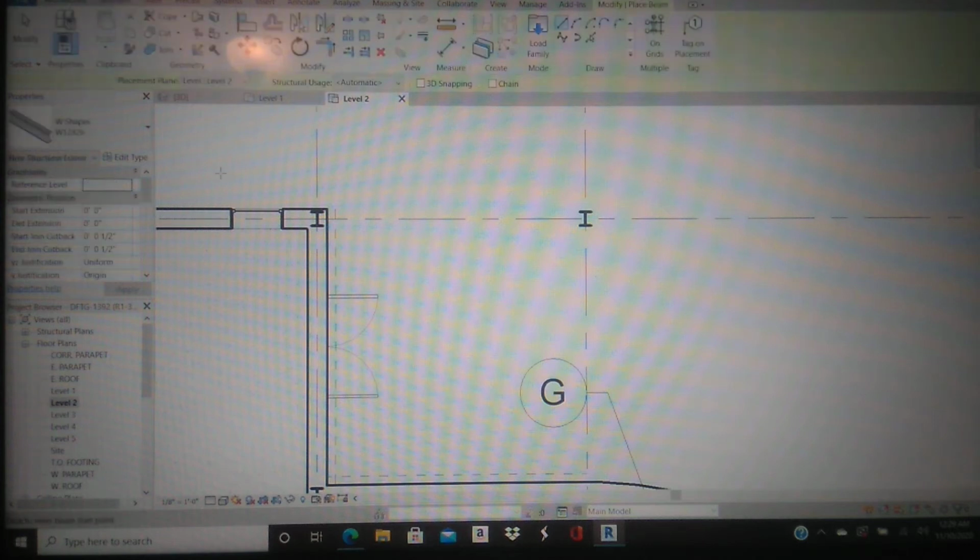So let's go ahead and click beam here, and we do have the 12 by 26 loaded. As stated, whatever you guys have loaded, I'm fine with that. We don't have to add tube steel, which is what I think the book is really calling for, a 6-inch by 6-inch tube steel. I just want you guys to understand how to bring in steel sizes, all right? Just learn how to bring them in. You can use those that are in Revit, and if they are not in Revit, you can click the load family button here. And if you're having trouble with that, when you're looking at this video in class, call me over, and I'll show you how to load families, okay?